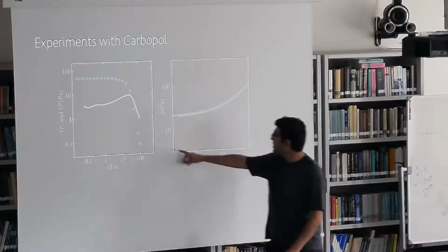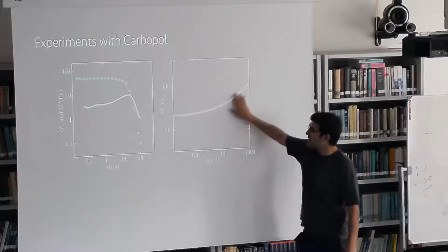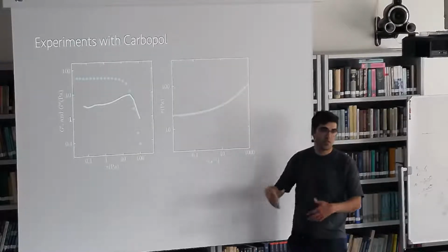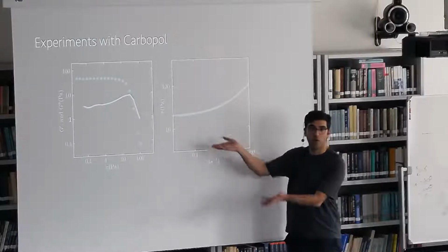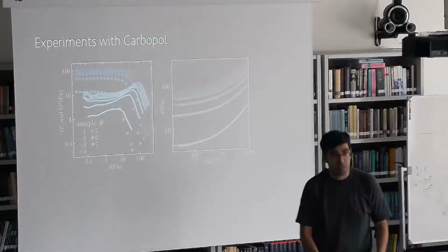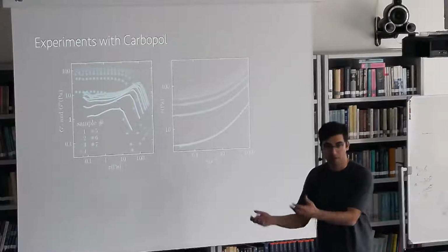After that, you can look at the flow curve that I showed you before, and you get these nice curves that show nonlinear shear thinning viscosity, and you can fit through it and characterize it. So this is a Herschel-Bulkley fluid, if you're familiar with it. And it's very easy to tune the rheological properties. You just change the polymer concentration, and you get different yield stress, G prime, G double prime, etc.